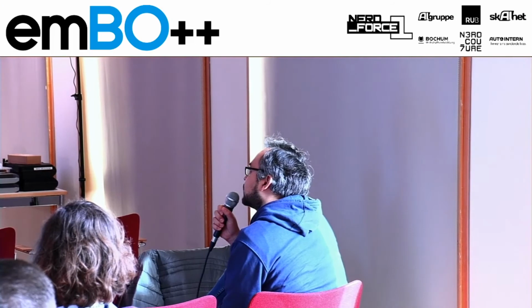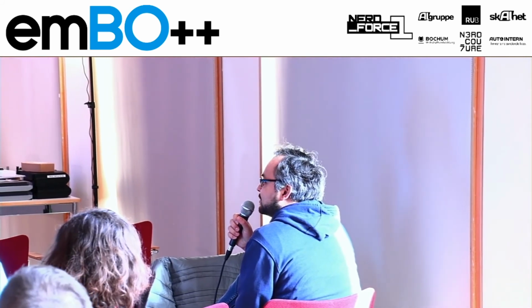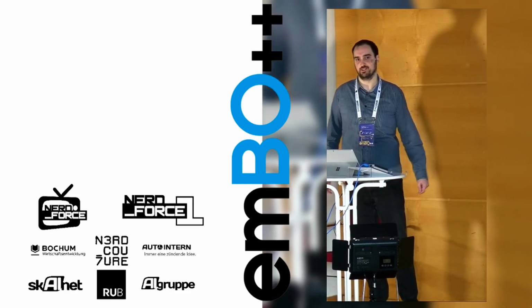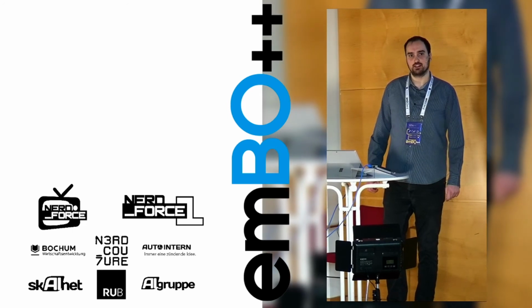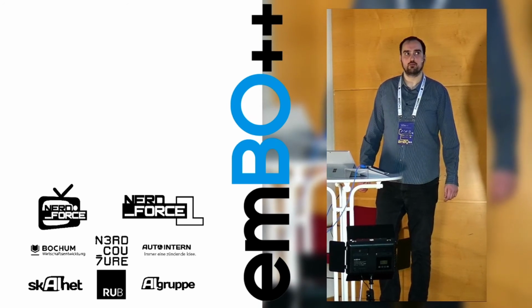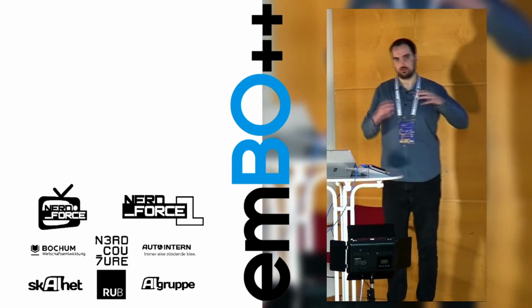So these 500 bytes, they are for the printf implementation, I guess, for the formatting and everything. Can I use it without? Like, what would it take to just write the string without the formatting? Well, you can of course link everything to RAM during boot, and then clear your flash if you need the extra ROM. But I don't have a lot of RAM space. So basically, I don't need printf. I just want to write the string, right? The thing is, we already have a pretty minimal implementation to create this buffer.